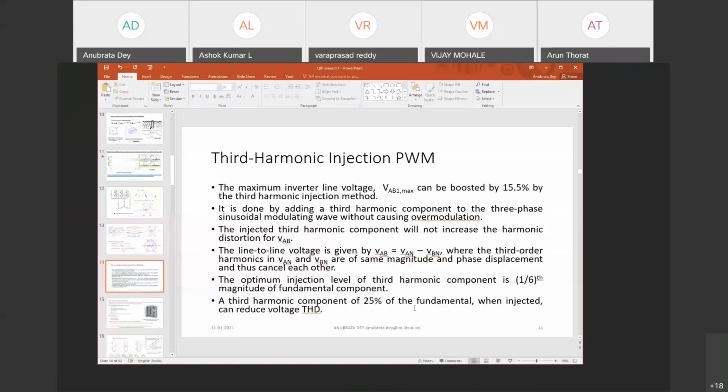All right. So till now we have understood the DC link, how we can increase the DC link bus, DC link enhancement. It can be done using some small technique in the PWM, either through SPWM third harmonic addition approach, or you can digitally add some offset so that the distribution of the timings can be rearranged, and it can be equal on both sides, first and last switching, or the zero vector switching timings can be made equal.